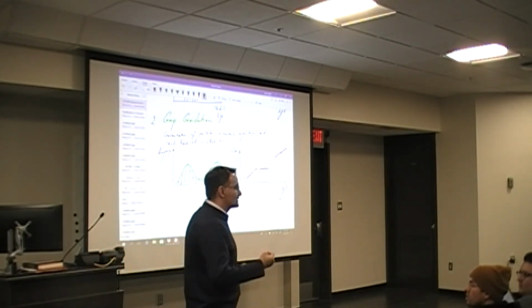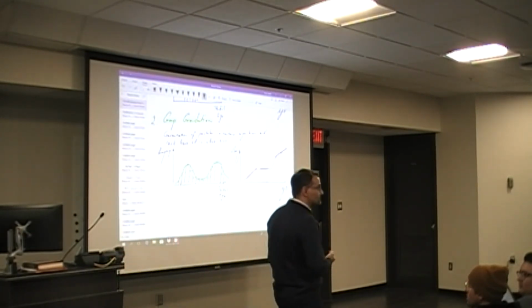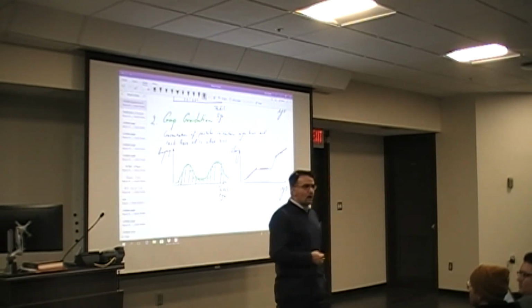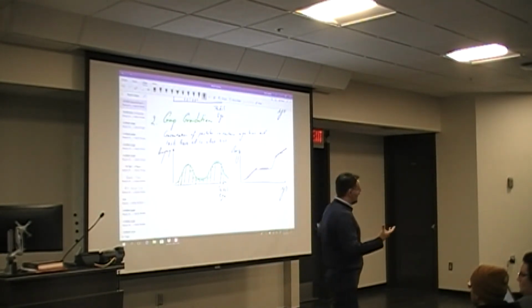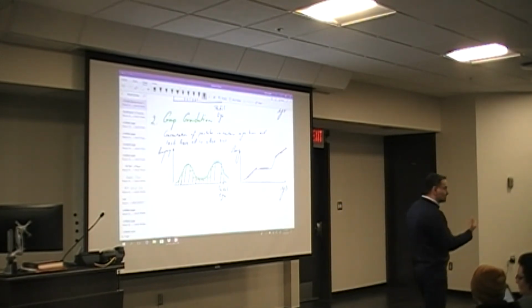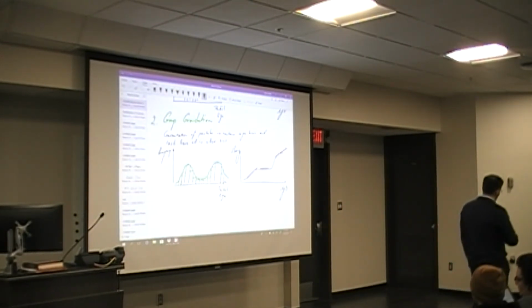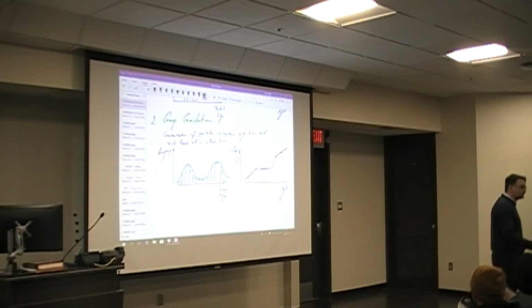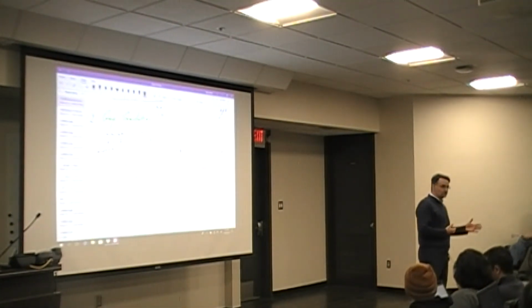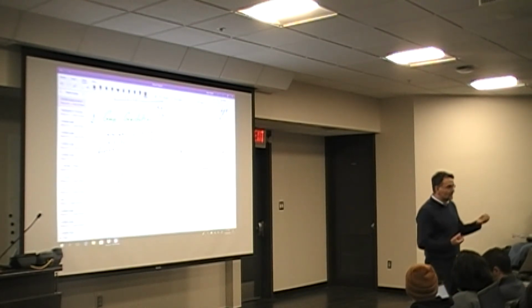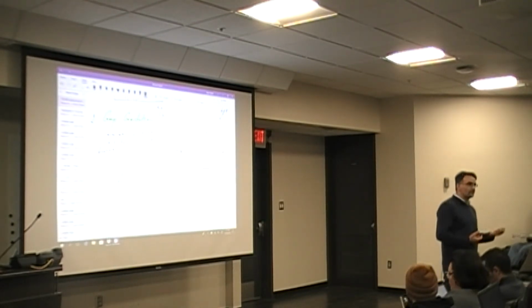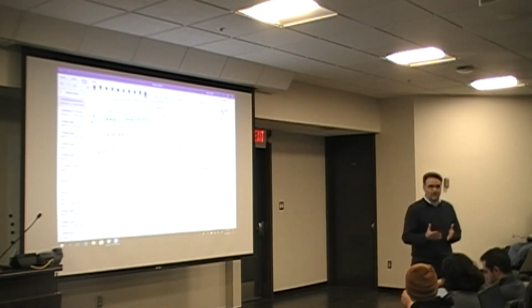So what happens when it crushes the aggregates? Yes, what happens to my gradation? My gradation will be messed up, right? The gradation is no longer going to be the same as the way that I designed it. Typically, particle crushing essentially translates into fines generation. There's going to be a lot of powdery material in there, a lot of fines in the matrix.